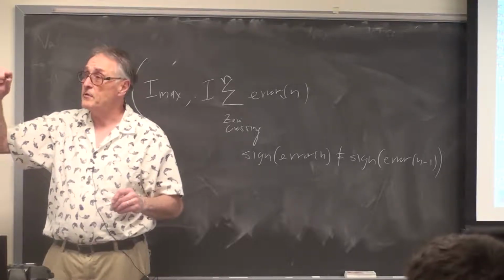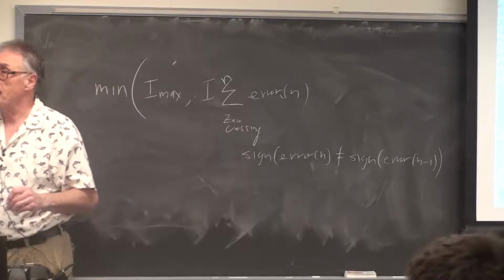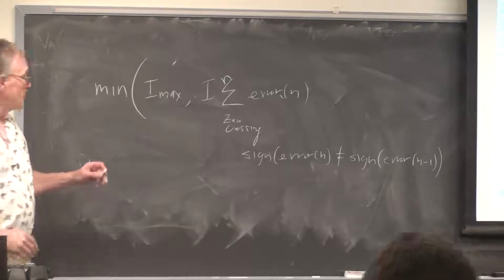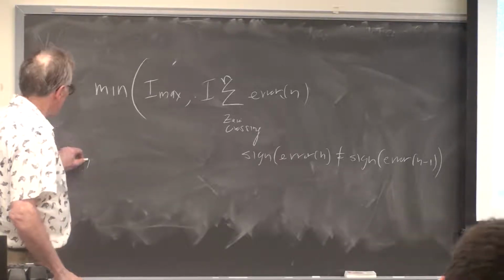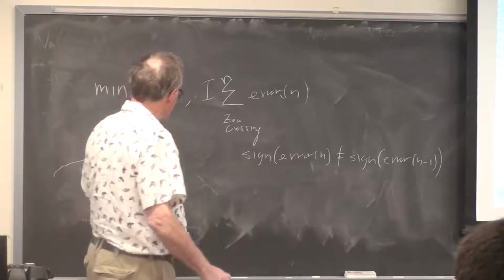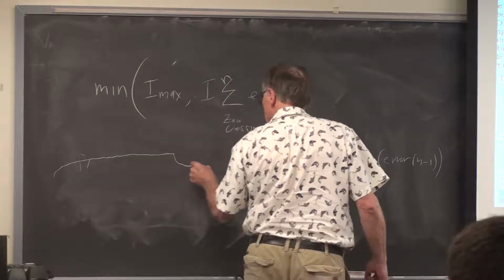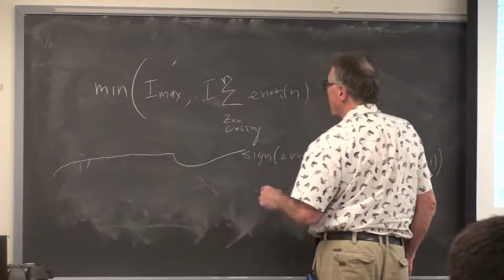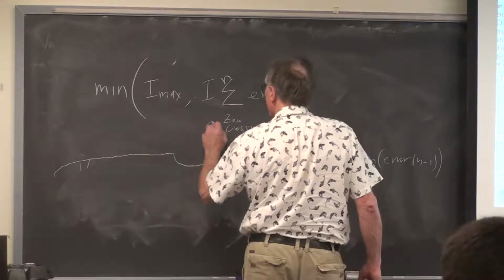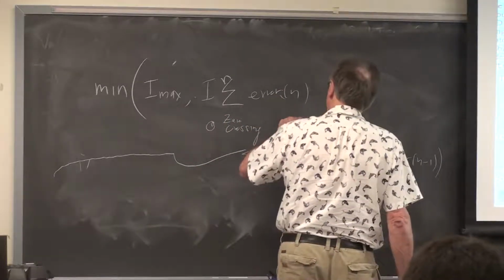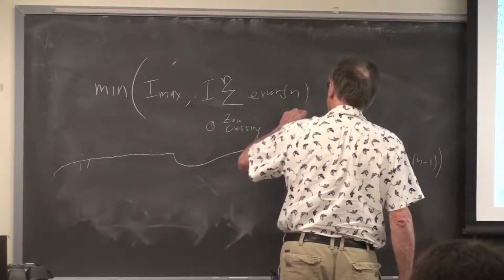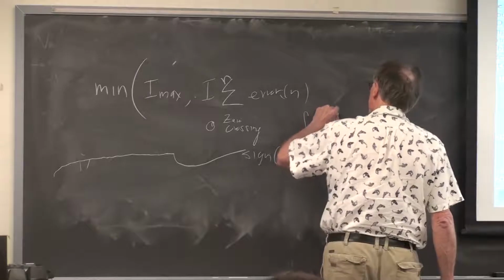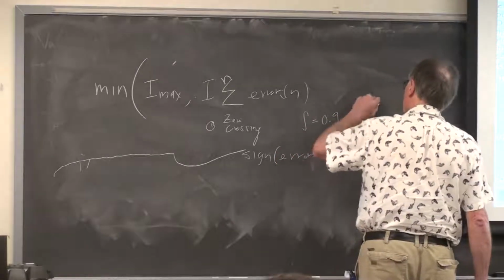But if you're getting a significant amount of your gain from that integral, when you zero it, the angle that's been creeping up will suddenly decay again and then come back up. So at zero crossing, you might want to say that the integral is equal to, say, 0.9 of the old integral.